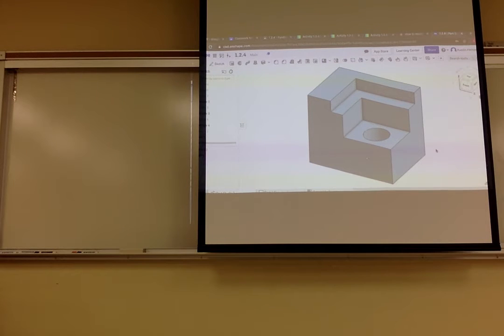And then right click on a view. It might be because you have dimensions. You'll probably have to do it one by one. You click on the view and you show the hidden lines. Okay. They're never turned on by default, not to my knowledge, but then it shows you your hole. Yep.